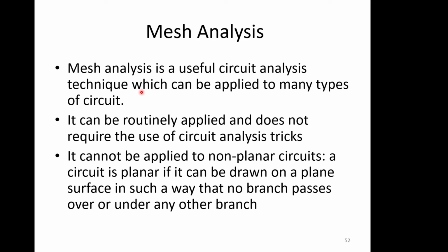So, mesh analysis. Mesh analysis is a useful circuit analysis technique which can be applied to many types of circuit. It can be routinely applied and does not require the use of circuit analysis tricks. It cannot be applied to non-planar circuits. So what does that mean? A circuit is planar if it can be drawn on a plane, a piece of paper, in such a way that no branch passes over or under any other branch. You can't have things looping over the top or going underneath. If you can draw it like that, you can apply mesh analysis. In practice, you can draw nearly all circuits like that if you apply Norton and Thevenin transformations to remodel your circuit to a different form.